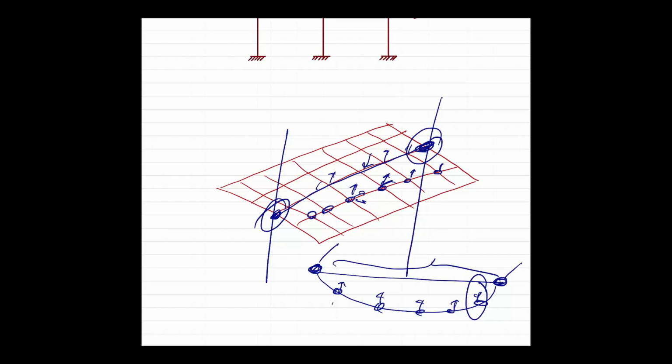Many people without education in the basics of structural analysis just believe, oh, the program is smarter than me. I don't argue with the program because I don't think I can do better, which is a bad and wrong mindset. Because when something like this happens, you need to check the program, you need to check the output, the deformed shape everywhere. Something like this happens, you come back and think, what went wrong with my model? And if you look into it further, you find that you didn't specify the degree of freedom along the beam.